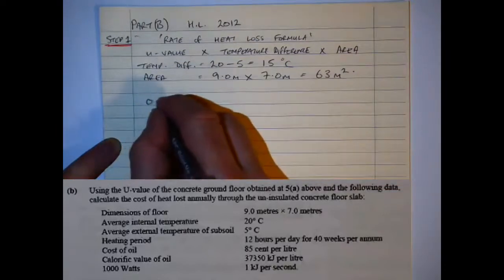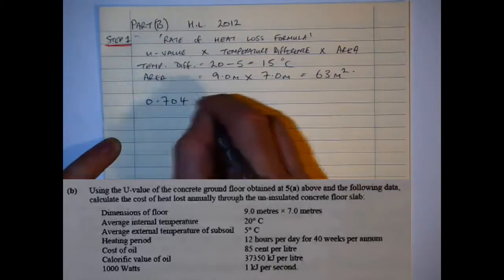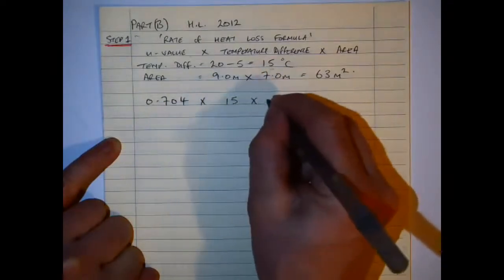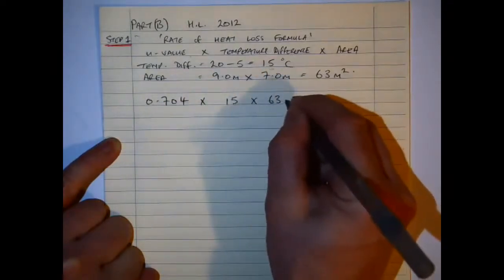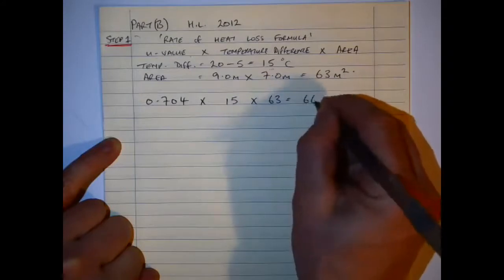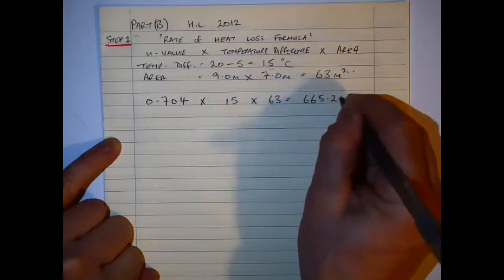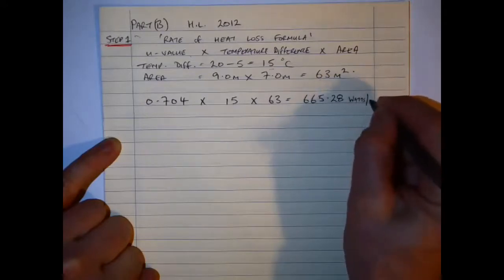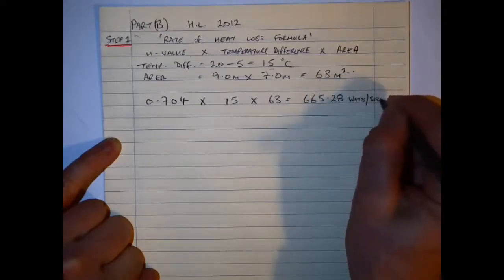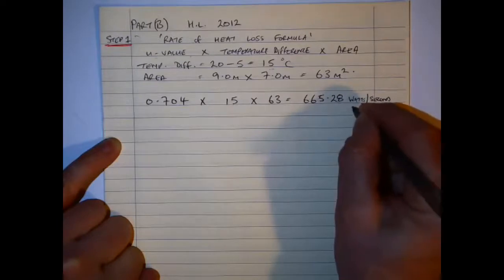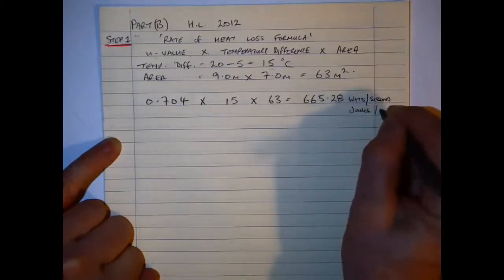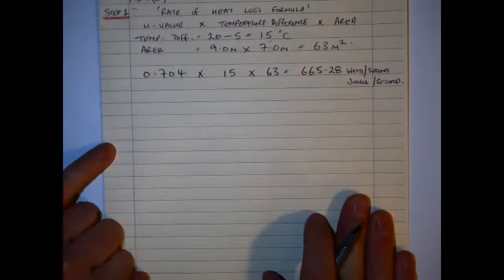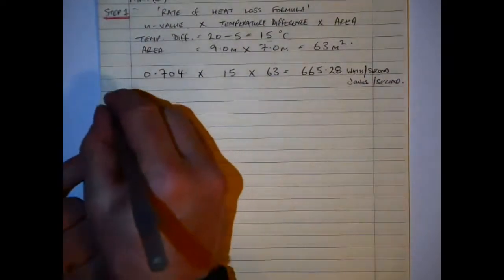So having calculated our U-value from part A, we enter all these figures we have now, the 15 for the temperature difference and the 63 for the area, and multiply this out. What this is going to get us is the watts or joules per second for the U-value, temperature difference and area. So that gives us our watts or joules per second. Our step two